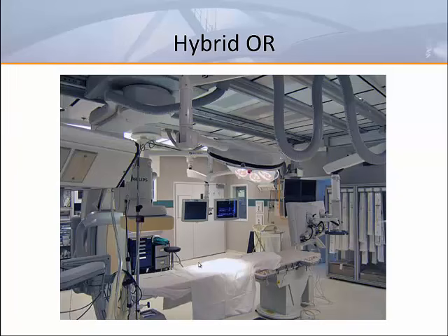As hybrid ORs are those that meet all the requirements of an operating room, they must also meet the air change requirements, diffuser array size, and all the other requirements stipulated by Standard 170 for operating rooms. In addition to the necessary HVAC requirements, there is a need for surgical lighting, numerous monitors to display information from the imaging equipment, medical gas connections, and diagnostic and monitoring equipment, all of which are commonly suspended from booms and mounts affixed to the ceiling.